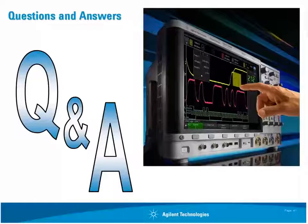But if you wanted to, for some reason, I don't know why, if you wanted to slow down your scope's update rate, if you put in a trigger hold-off of 1 millisecond, then the scope would trigger on an event, then it would disarm triggering for 1 millisecond before it rearmed the scope's triggering, in which case the maximum rearm rate would be 1 millisecond or 1,000 waveforms per second.